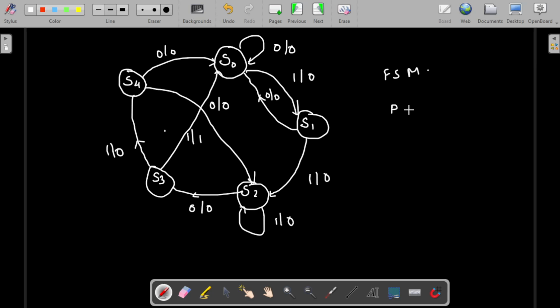Here you can analyze the present state, next state, input and output. You can try both Mealy and Moore, but here we have used the Mealy system only. You can try the Moore system too, but for sequence detectors we mostly use Mealy because it is easier to analyze. If the Moore system is used, the output will be presented inside the state, after the input bar. That will be the only change.